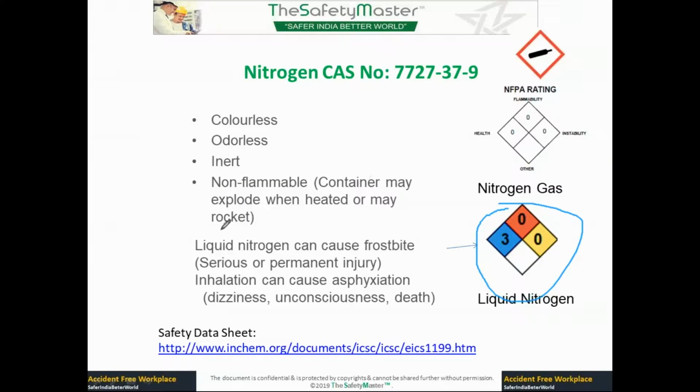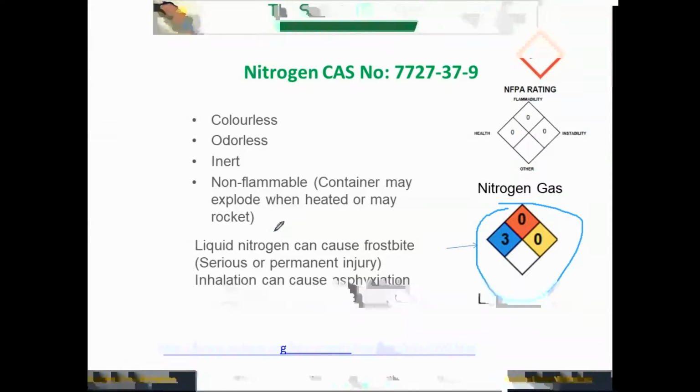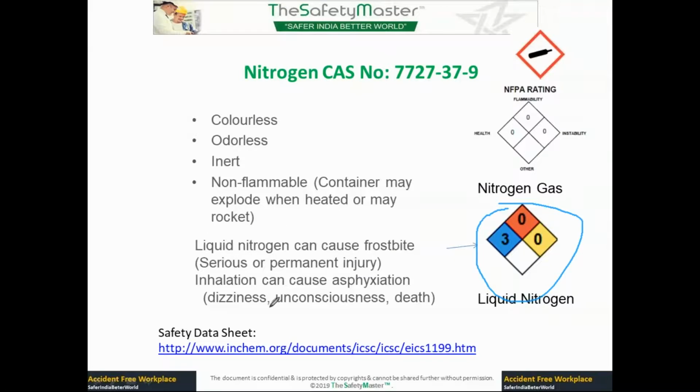Okay, but containers may explode when heated or may rocket. Suppose you heat a Dewar, or you heat a liquid nitrogen container. Then the vapor will vaporize very fast, and then it will explode. Same with gas cylinders. So first there is a safety aspect of it, but the moment you suddenly increase the heat, the safety may not work so much, because the rise in pressure is so high that the whole thing will explode. Okay. The health hazard with nitrogen is frostbite.